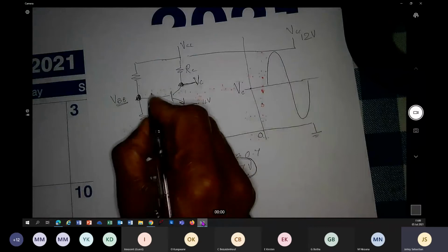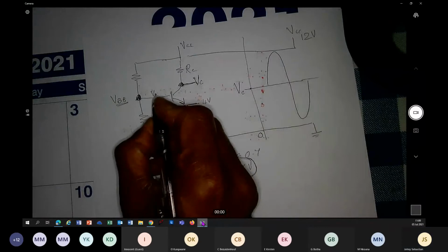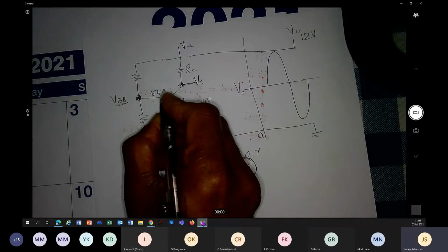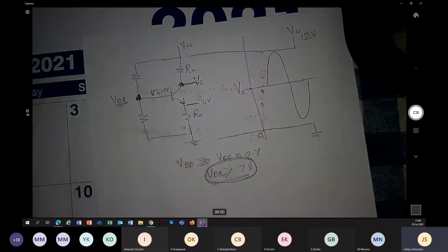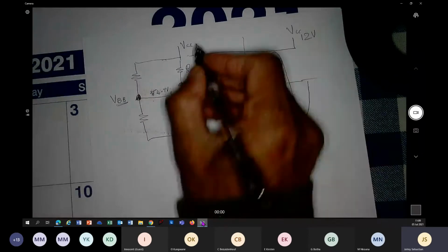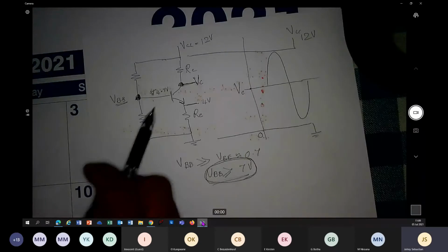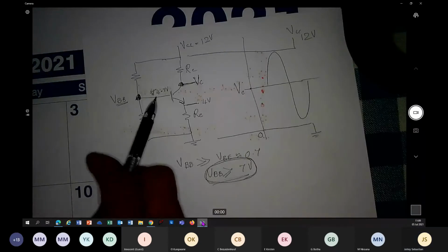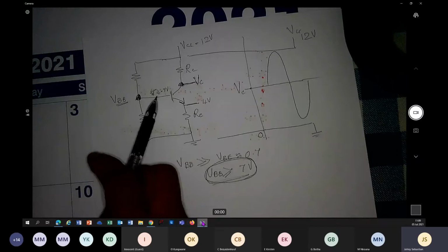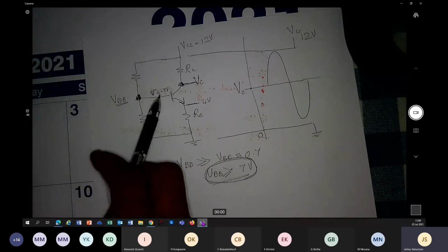Voltage at the base is going to be 4.7 volt. That is for a power supply of 12 volt. Now look at the VBB we have. Is it very much greater than VBE? Not strictly. Strictly, it must be around 7 volt, but we cannot afford that high voltage. We are compromising on the voltage.